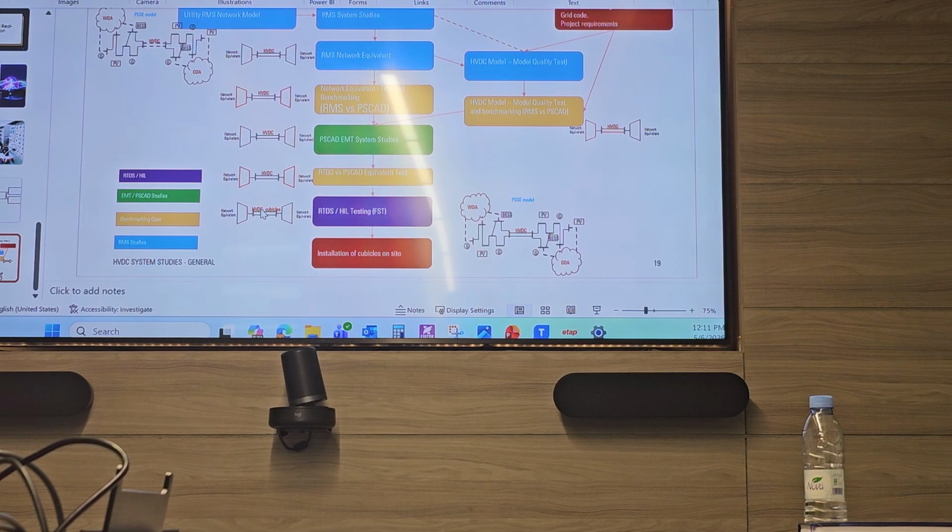So the main issue here is that, for example, if we disconnect or overload the system, the change in natural generators that we have will be by inertia. But in DC, the power electronics have to compensate for that. Yeah. So, for example, they need to do higher switching or lower switching. That's the main issue. Basically, they need to simulate inertia. There is a terminology called artificial inertia.